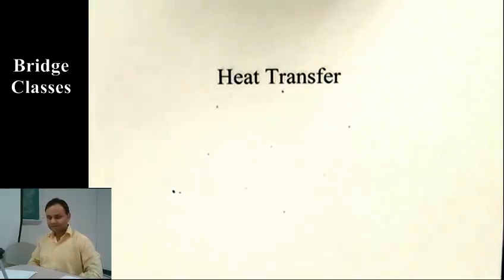We have been discussing the topic of convection, and I discussed that there are 5 methods you can have to determine the convection coefficient. Again, just for review, we can use CFD, and we have the governing equations. That is one. We can use dimensional analysis along with experiments, so we'll have a correlation for heat transfer. We can do an analysis of the boundary layer equations. Blasius solution was an example of that.